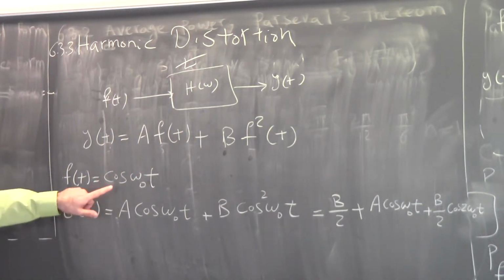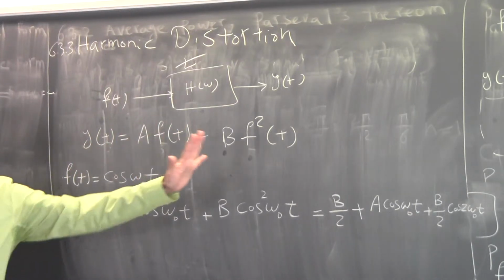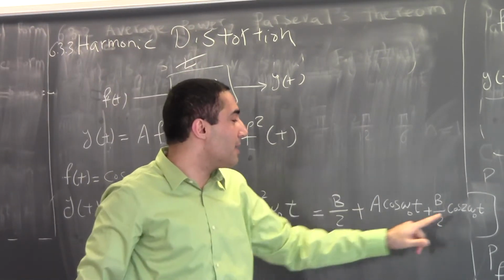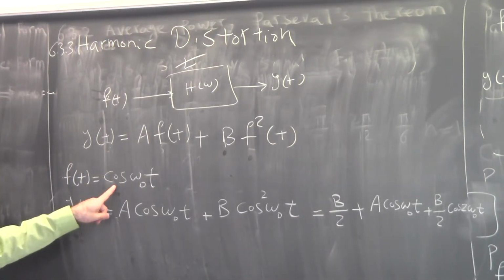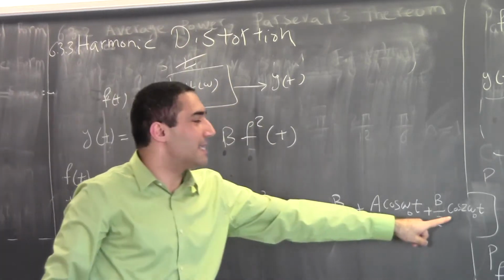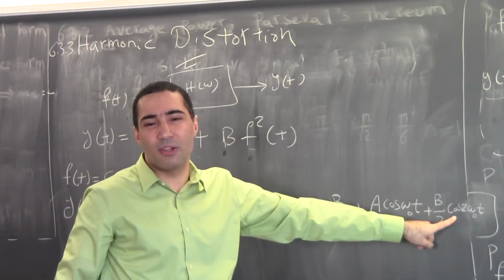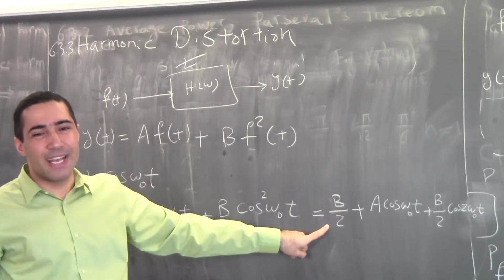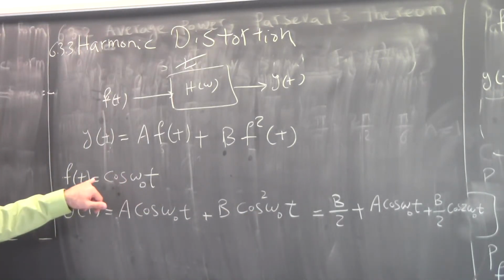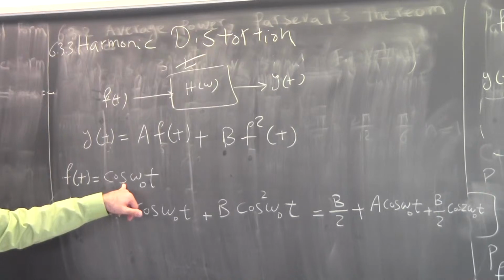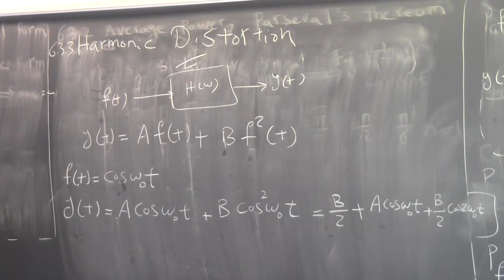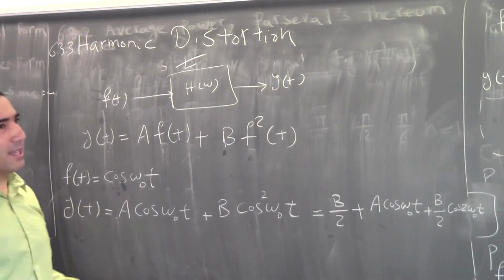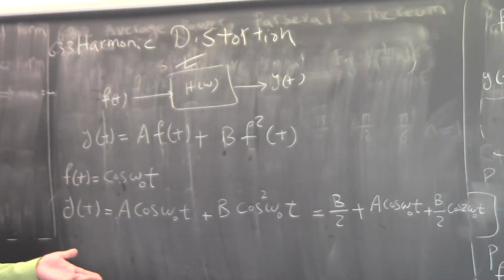You enter one harmonic signal to your system, one tone signal that has only one single frequency. It goes to your system, and your system generates a signal with double that harmonic, double that tone, and also a DC. So you know what's happening to the energy of the signal which was initially stored in this signal? Now it's divided between 3 components. This is not wanted on your board. Any board designer tries to avoid generating other harmonics. And unfortunately, this happens in real life.